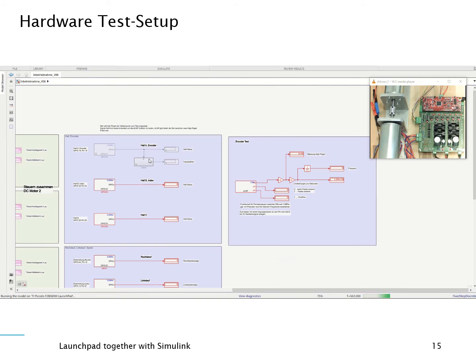The hardware is built in that way. I can use either a Hall sensor for brushless motors or an encoder, like I use here for my DC motors. We cannot use them both at the same time, unless we use two digital ports. In this case, I do not.